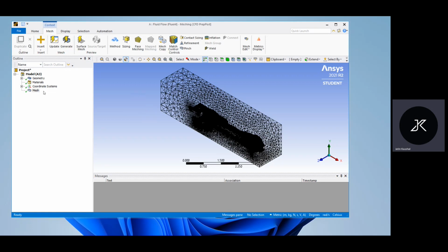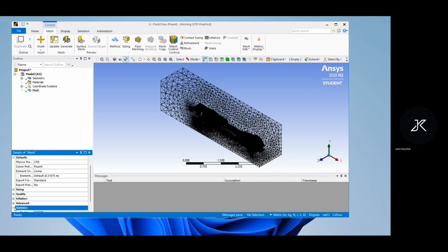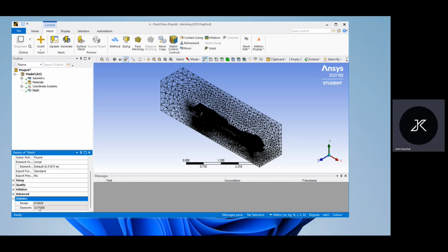So our meshing is done. We can see details here. Here it is showing the number of cells. A cell is like a triangular or quadrilateral structure, which you can see. Currently there are 3,277,000 cells, but in the ANSYS student version, only 500,000 cells are allowed. We cannot do calculation with more cells than that. So we will try to reduce the number of cells here.